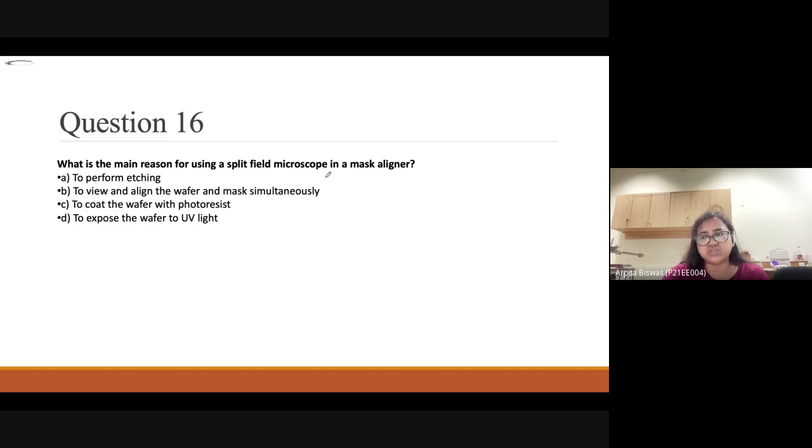if we coat the photoresist and we want a stable layer. If we do not heat, the bake process means we are heating the wafer. So before the development process, we have to go for this heating process, otherwise it will be removed easily.